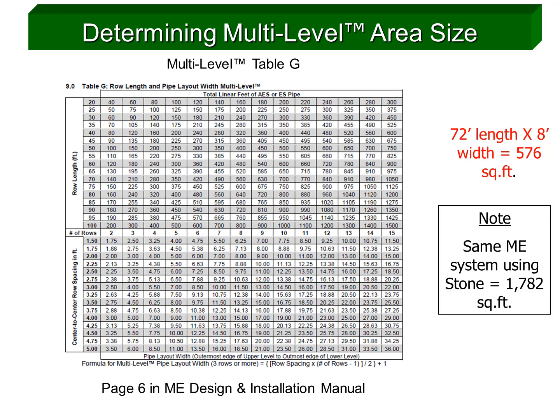Let's summarize the field we just designed. For our 6-bedroom daily flow, or 540 gallons per day, we will need 6 enviroseptic rows, 70 feet long, with 3 rows in the upper level and 3 in the lower level, spaced 2 feet center to center, resulting in a pipe layout width of 6 feet, and utilizing basic serial distribution. Let's take a look at an illustration of this field.